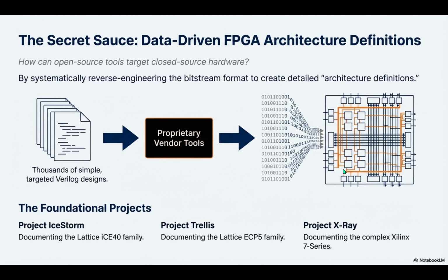It is. The sources basically describe these engineers as digital archaeologists, and the foundational projects are amazing. Project IceStorm successfully documented the Lattice iCE40 family. Project Trellis did the more complex Lattice ECP5. And there's one for Xilinx, too. Yeah, the really monumental one is Project X-Ray, which is tackling the incredibly intricate Xilinx 7 series architecture. Without these reverse-engineered maps, none of the open-source tools could function.